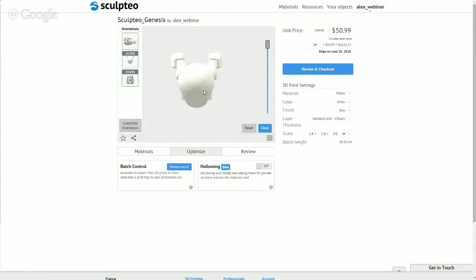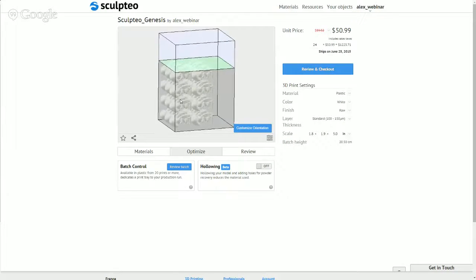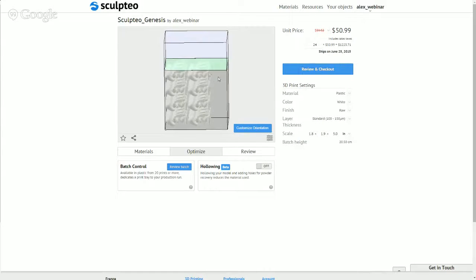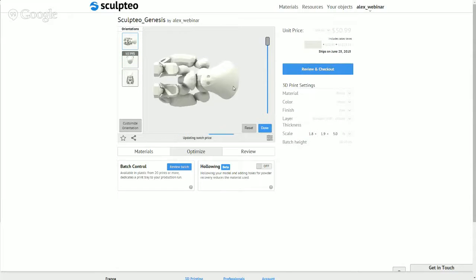Well, it depends. You can see that this orientation was at $40, but this orientation here is really bad. It's at $51. So we've only saved $8. It's funny to talk like that, saying I only saved $8, but it's still 7 or 8% there already, but that's because when they're laying flat on their bellies like this, we're not using all this space properly. So you're actually better having them standing up, or maybe change the orientation a bit like this. Maybe this will work better.